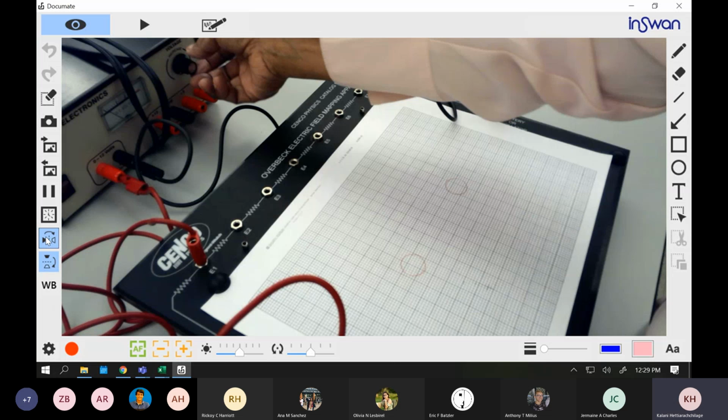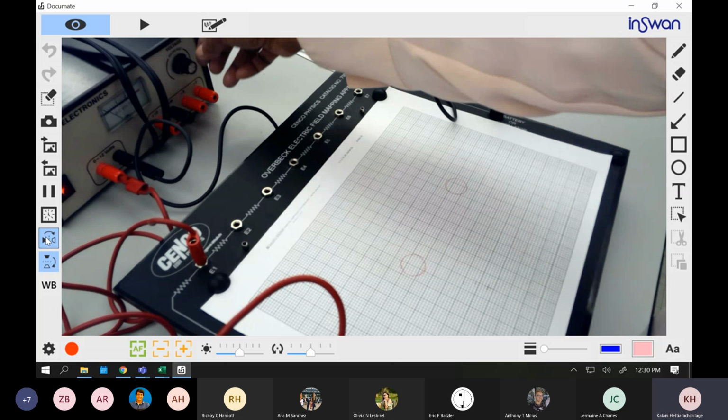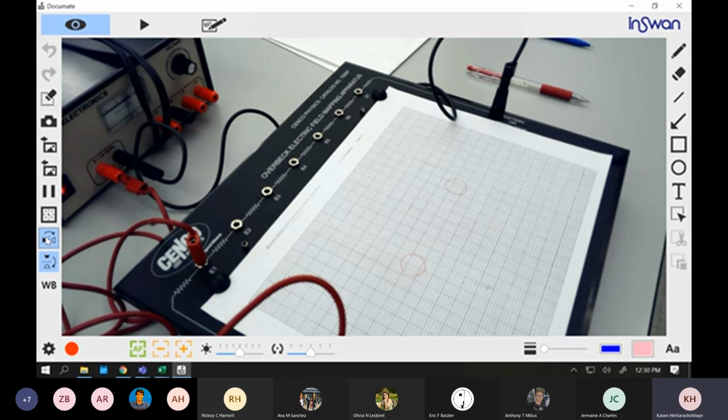Now you're going to switch on your power supply with the on button. Now you will see the lights, right? And now rotate your knob to check the reading. Here you have DC volts, and increase it to 10. Usually when it starts it will be 0. So you want to increase it to around 10, not exactly 10, somewhere around 10. Okay. And so now you have the voltmeter. You need to switch it on first. There is a switch on button in here.